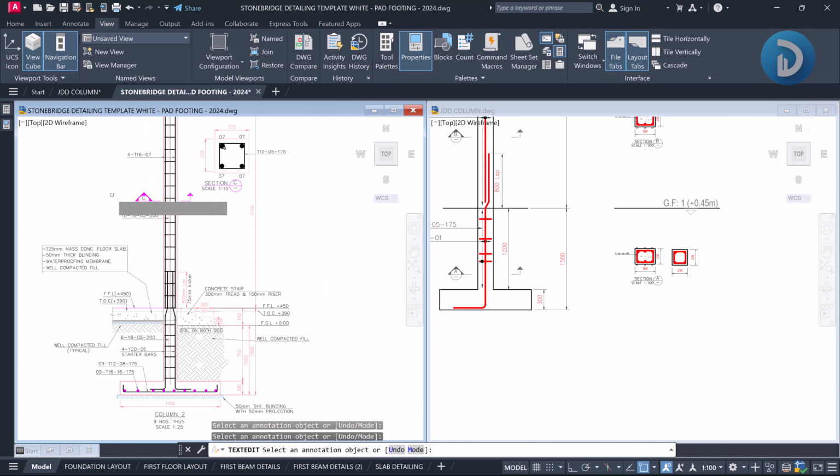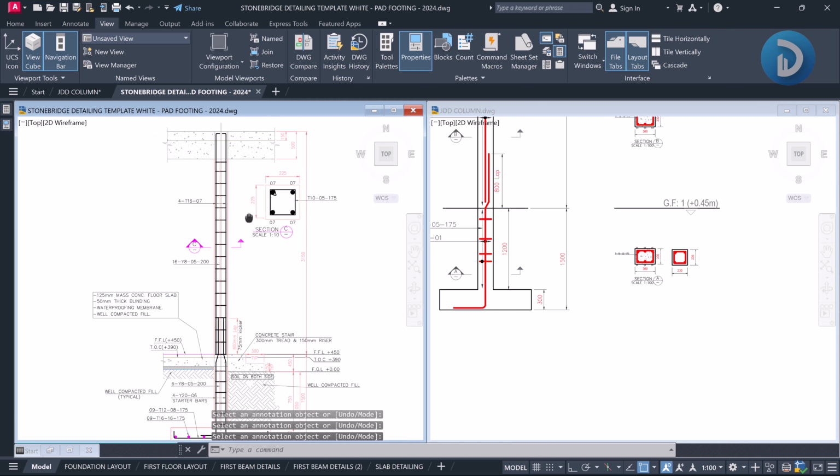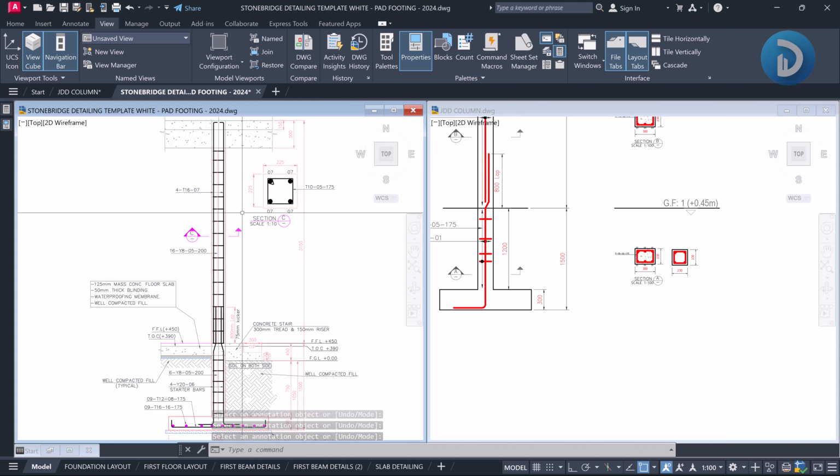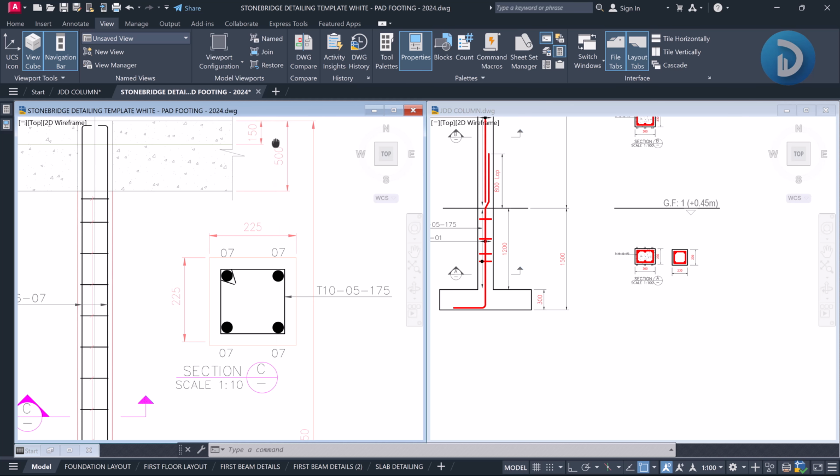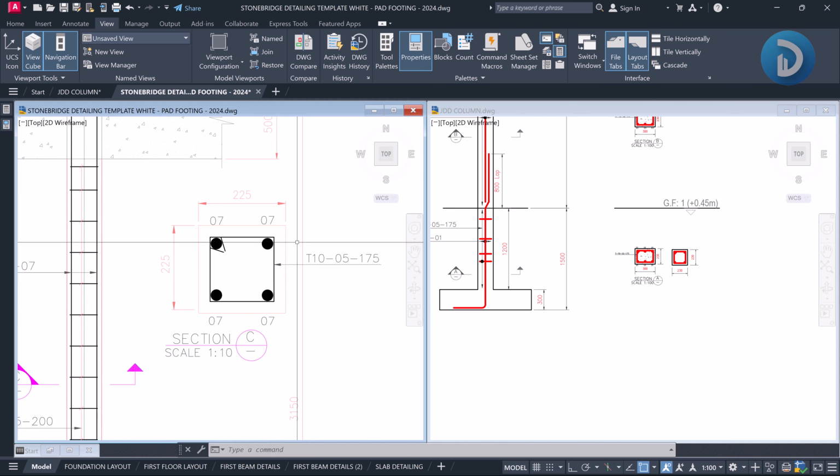All right, so like I said in our previous video, what you should understand is if you intend to get the adequate numbers of shear reinforcement required for this story, then you have to take your dimension from this point to this point and not the total story height. So it means you have to subtract this 500 millimeter from 3.15 meters.